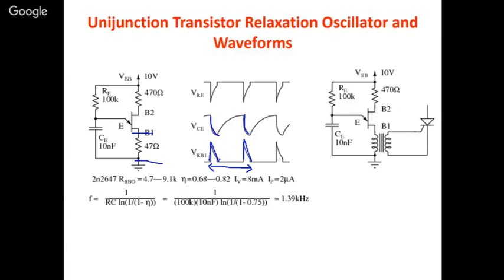Both of the things: the pulse width can be adjusted by changing the RC value, that is the time constant there. If your drop is a bigger drop, automatically your pulse width also will be bigger. So this slope can be adjusted by the RC constant. When you adjust this R and C value, automatically the slope can be adjusted.